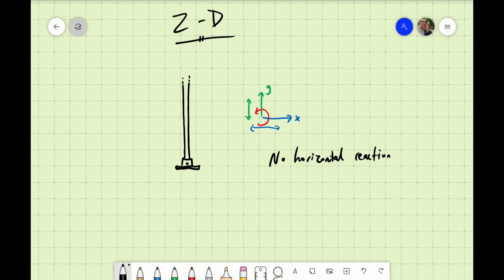That tent pole can also rock left and right. It's not likely to do so very much because there's the whole superstructure, but if you forgot all the superstructure and the canopy and everything and disconnected that, there'd be nothing stopping this tent pole from rocking left or right in the wind and falling over. So there's actually no moment reaction either. There's no resistance to any moments that might happen. Like if the wind blows, it creates a force, there's a distance, that is a moment. That's what makes it rotate and fall over, and this wouldn't stop that.